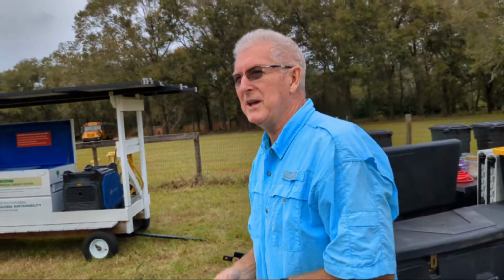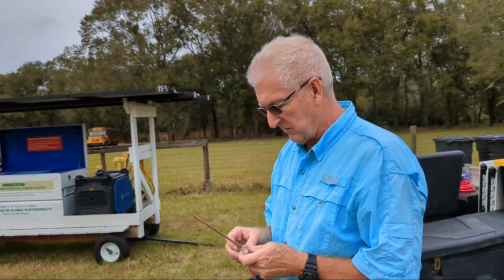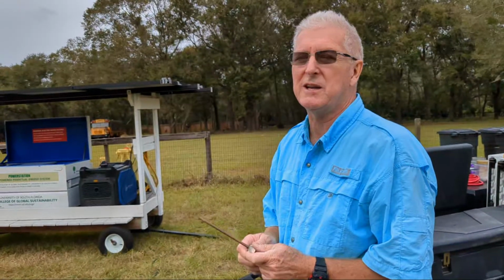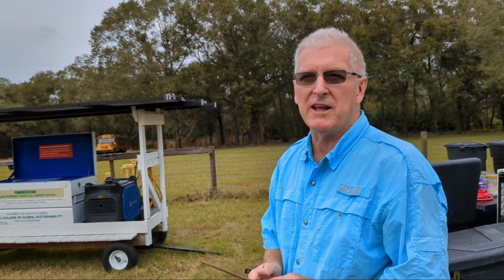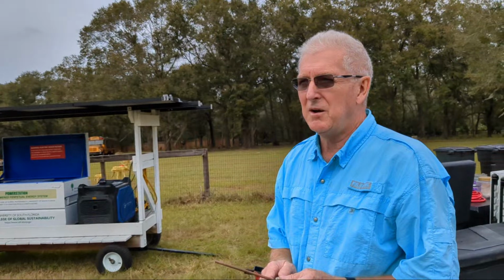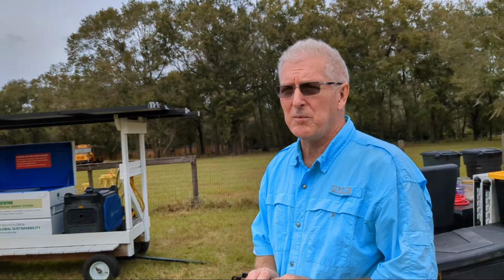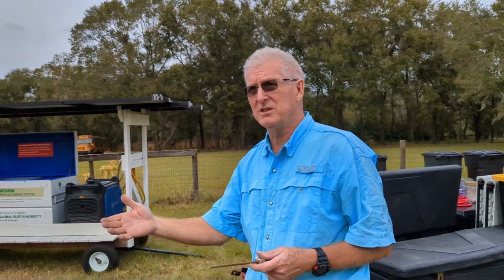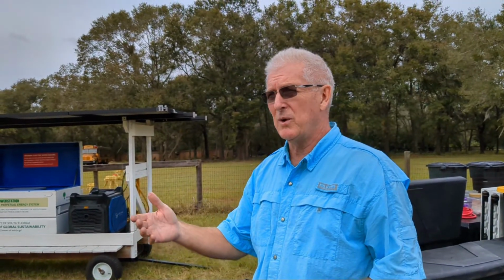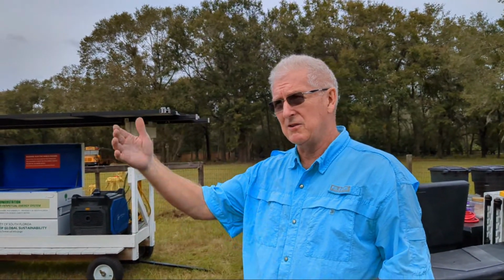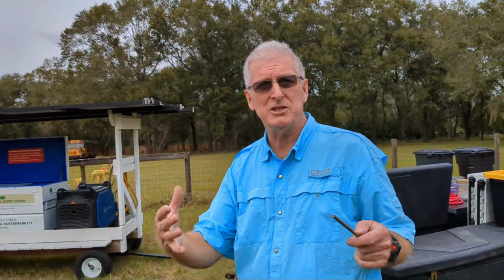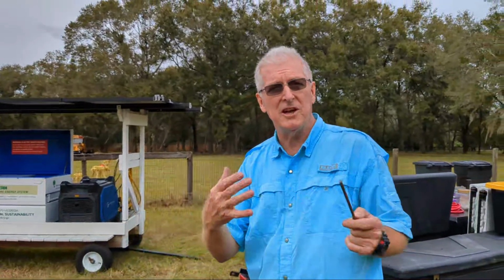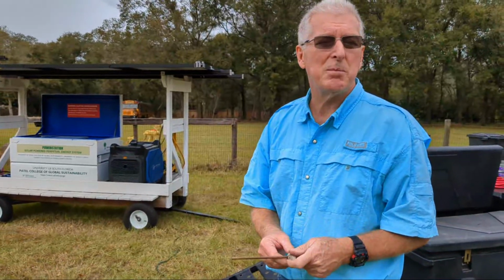There would normally be, but I can't attest to the fact that there is on this inverter because this inverter is designed to be grid connected. Whereas an inverter like a Victron Energy inverter is designed from the beginning to work in boats and RVs where they're sometimes off grid and sometimes connected to the grid. Because of that, built into the device is an automatic switch that will switch from one condition to the other. There's no such capability in this inverter.